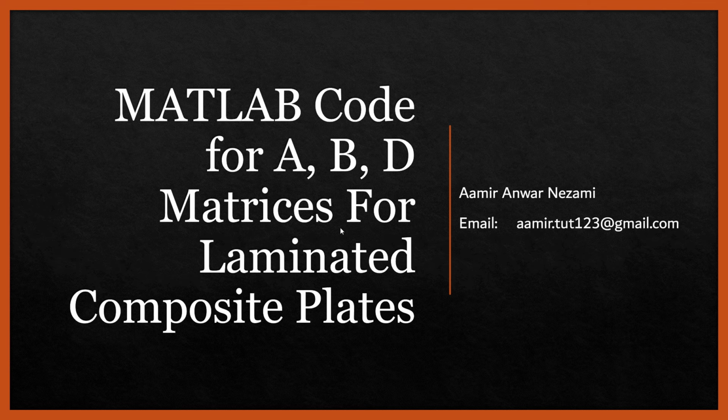Basically, we have already read the various classical plate theories, first order shear deformation theories and all, but some of the viewers have asked that, sir, I am not getting the basics as I haven't covered them. So they have asked for lectures on the ABD matrices. For the laminated composite plates, in the classical laminated theory, we have just made the ABD matrices. So how do we code for it?